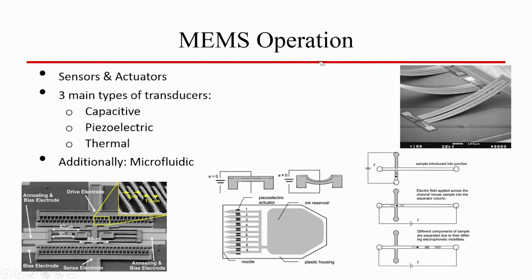Another point, that is piezoelectric. There is a very distinct difference between piezoelectric and piezoresistive. If I say piezoresistive, what does that mean? Piezoresistive components are components where, when we apply a pressure or a force, there is a change in resistance. Alright, these are piezoresistive. In case of piezoelectric, when you apply a pressure, what will happen?